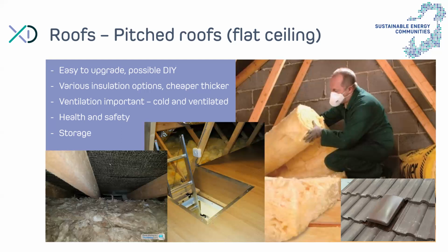The same would apply to downlighters. What would have typically happened is the insulation is laid around those downlighters, but that leaves a significant space of ceiling not insulated, and a big gap where you can have a lot of air movement. From an air tightness point of view, if there are downlighters in your house, I can guarantee you these are an important source of heat loss.